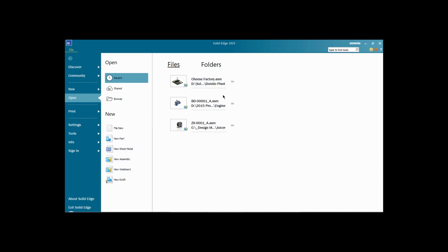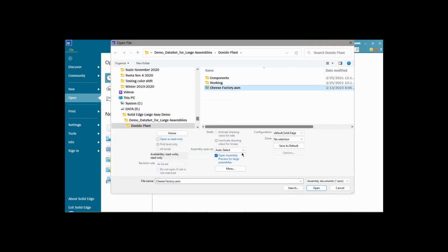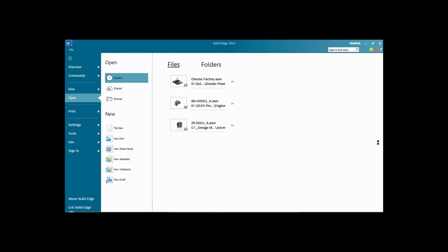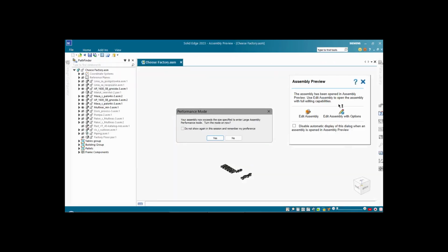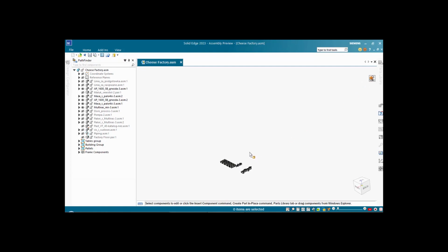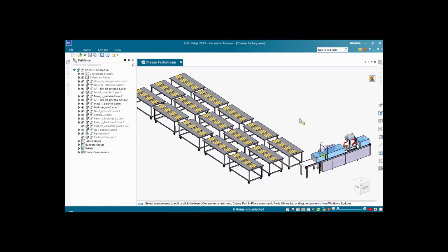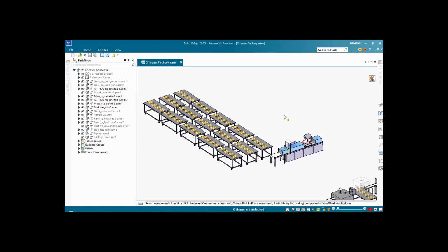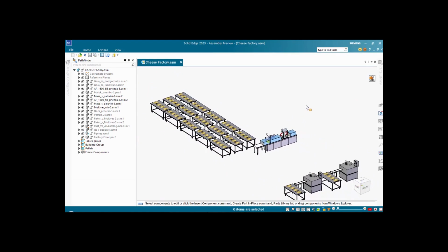So when we select all the options we selected before, as far as configuration, we can select any specific configuration. And if you know a configuration which limits the number of components, that would be great. Let's say assembly snapshot. Because preview is turned on, you can easily open that. It takes no time. And the same way you can go and measure and do the same thing, assembly statistics, like we did with the whole assembly preview.